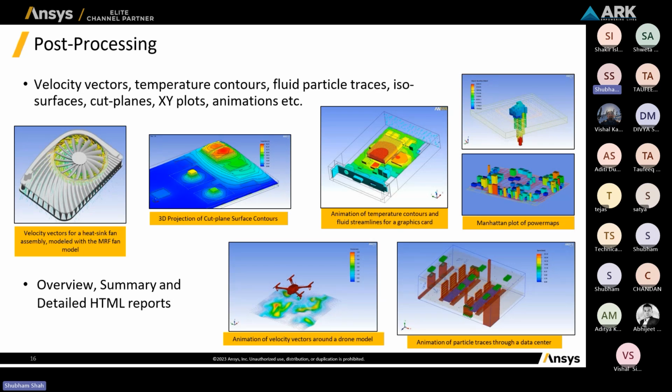What are the different input conditions, boundary conditions you have selected, what are the physical models. When we talk about the physical models, I mean here the turbulence models. What is the turbulence model which you have taken, how much time you have run the simulation. Let's say you are running a transient simulation, for how much time. Let's say you have run the simulation for 5 seconds or 10 seconds, it will indicate the solution was run for 10 seconds. And what are the different contours you have plotted, it will also be included in that report. So it will give you an overall report from start to end, what are the different operations you have performed during your simulation.